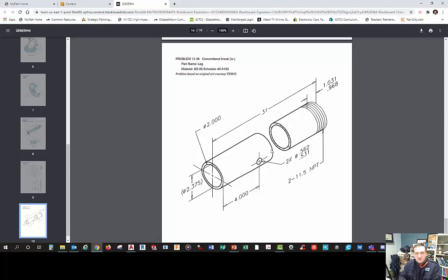You just need to draw the end of it and the end of it, and if there's a feature over here, you draw that much, but then you can leave out a bunch of it and just shorten it up so it doesn't take up a big chunk of a piece of paper just for this long object that's the same. So what we can do is cut it out, and then we can do a broken dimension.